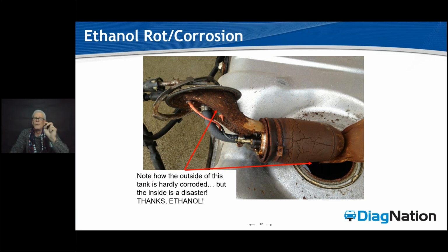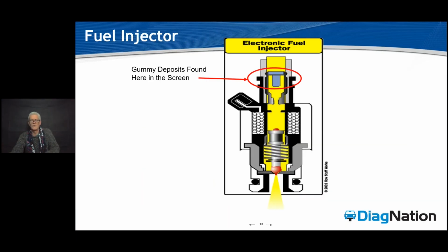But you have to think about all of the metal, steel, and aluminum that it still does contact within that fuel system. Okay, we're still getting some corrosion, not anywhere near what we did in the old days, but we still are getting a lot of that fuel breakdown and problematic clogging of the injector screens. So that's something to watch out for.